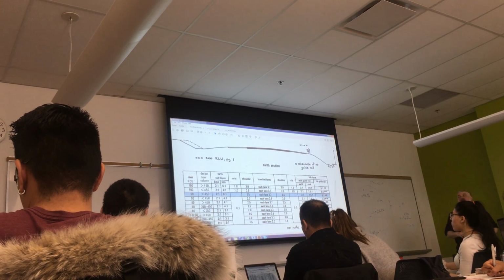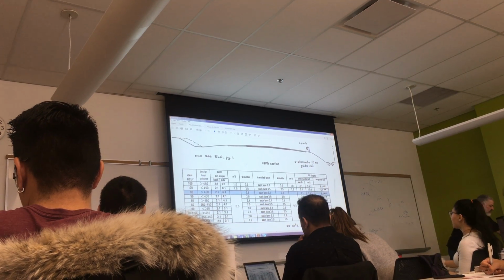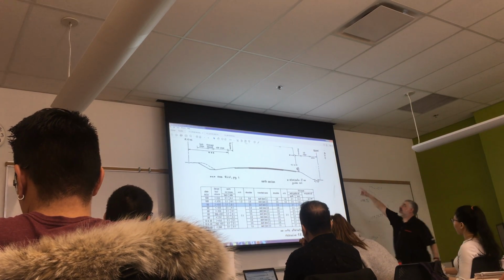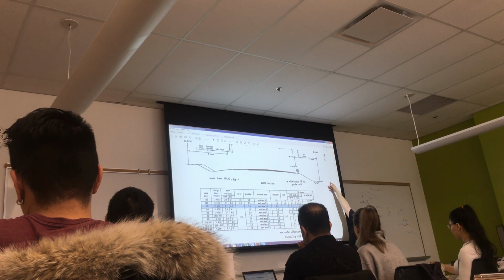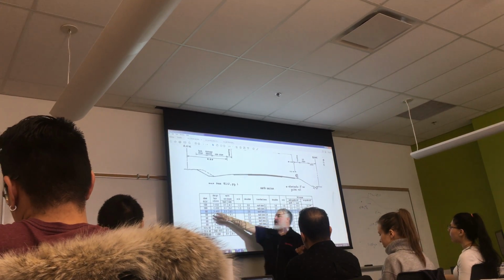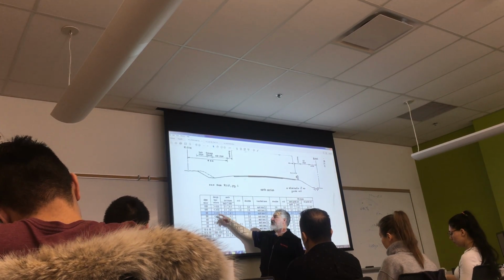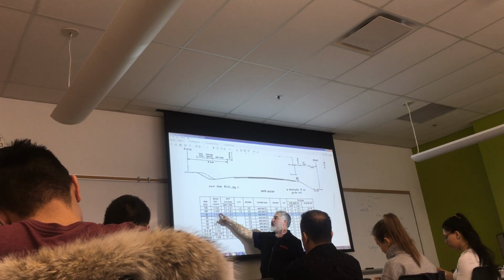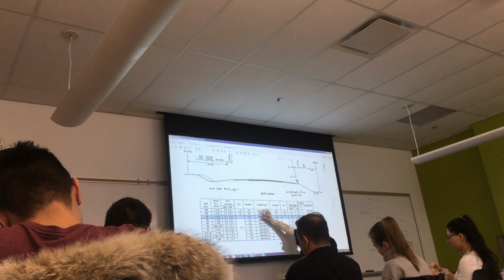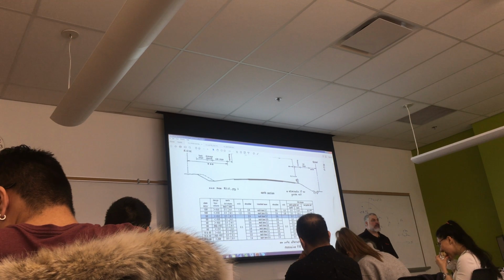I'm here? I know the road classification, right? The page is labeled right here, RCU. RCU, I know it's 90 kilometers per hour, so it's one of these. And then I'm also given the design hour volume greater than 450. So all the information I need is in this highlighted blue row. Okay?